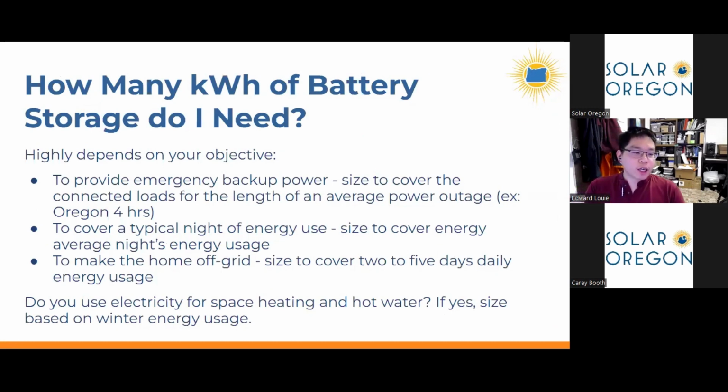And so if we're talking batteries, then a very logical question to ask is, okay, how many kilowatt hours of battery storage do I need? And that really depends on your objective. You can either size it small enough just to provide for a power outage, or size it large enough to cover multiple days of energy usage if you're going to go off grid. And there's not really a right answer. That's a decision you have to make. And for sure, if you use electricity for space heating and hot water, then you want to size the battery for the winter period, so at least maybe the winter 6 months. And so that's something to think about. Next slide.